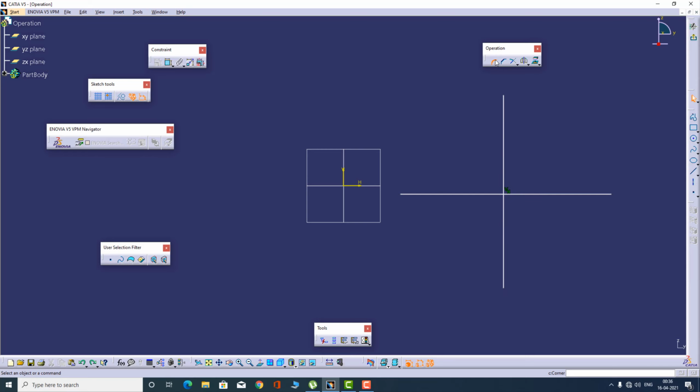Let us see other options, which is the last option, basically construction lines no trim. In this case the lines will not be trimmed, but they'll turn into construction lines up till where the corner actually meets the lines. Okay, let us make this as well. We select the lines. So here you will see the lines are actually turned into construction, they are not trimmed. Okay, so this is another option that you can use in corner.